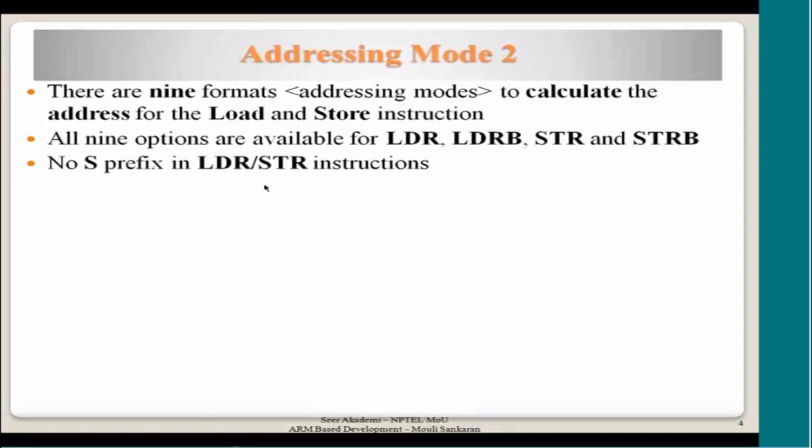So this is about getting data into the processor or out of it, and there is no data processing involved. For that reason, the S flag is not affected by LDR and STR. The condition flags in the CPSR are affected only by data processing instructions, not by data transfer instructions.